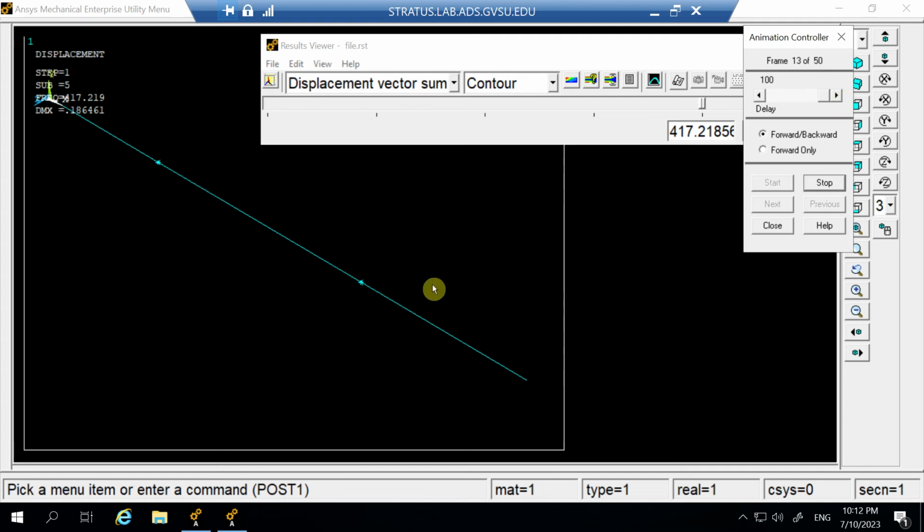So the chance of that getting excited is lower. This is axial, not the torsional one. Obviously this is going to be just one, not two of them, not repeated, because there is only one way this can be vibrated axially.